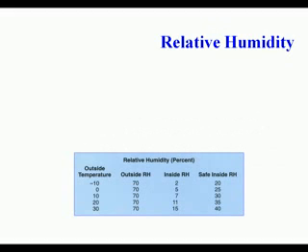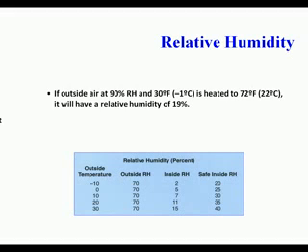The humidistat is used in a humidifier to control the level of relative humidity. Too much humidity causes swelling of wood products and condensation on cold surfaces such as windows and window frames and doors. Water vapor may condense on the inner surfaces of outside walls. Excessive humidity should be avoided as mold and rot may occur at 70%.